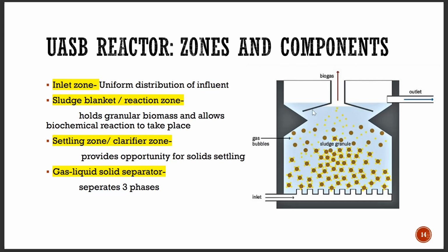Only gas and water will be there. So gas will be taken out through this gas collection chamber, and water is taken out through this outlet, and the solids are allowed to settle in this particular chamber itself at the bottom. Okay, so this actually serves as a clarifier also.